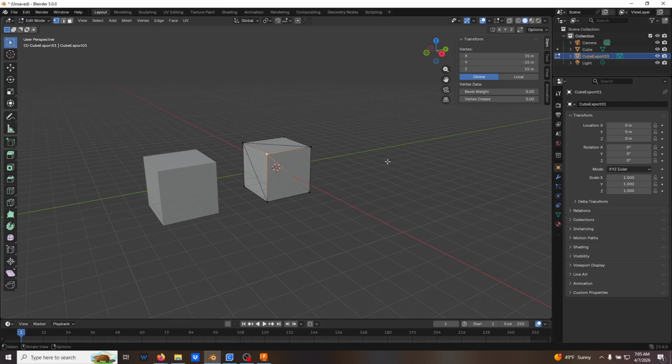Okay, this highlights a couple of other things which I'd like to think about when working with these objects. The scaling is important, for a lot of reasons really. Even when it goes to texturing and applying UVs, it can affect how modifiers will work with your mesh. Another thing you can do is use the scale and manipulate it to help with your modeling as well. But it's super, super important. What I want to do here is talk about the importance of applying versus clearing.